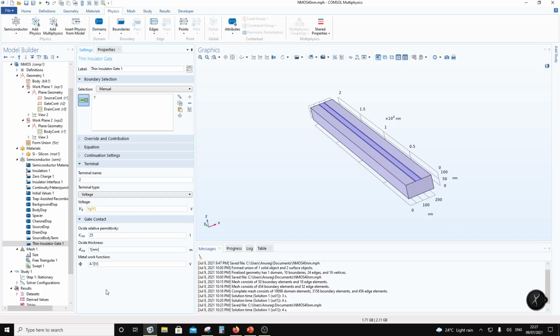So the first term is VT0, the second term is going to be the body effect term. If you want to know what that is, you have to go to my playlist called Analog Integrated Circuit Design using ADS. There I have detailed what the threshold voltage is going to be. So that is a semiconductor work function over here, 4.1.